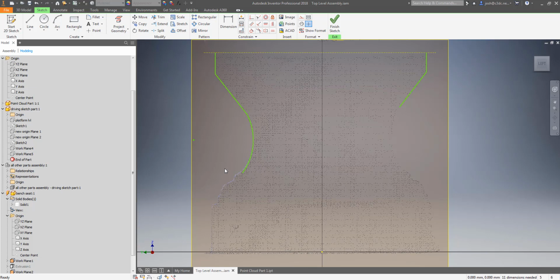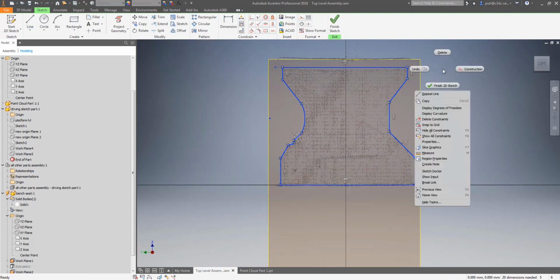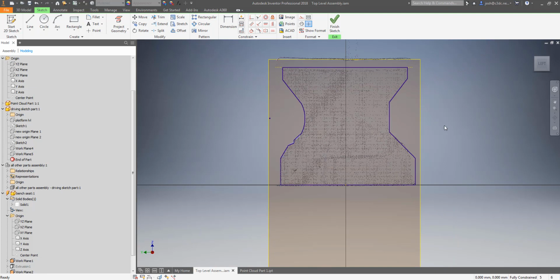They will either only do a patch of the wall, a part that is flat enough to fit into the limit of the algorithm, or, if all of the points on the wall fit into those limits, they will do a flat patch where there is a bent wall. Neither of these results is a particularly good one, and both are a long way from the ideal. When you consider that solids created using this method can be very difficult to use in drawings, it really isn't a great way to work.